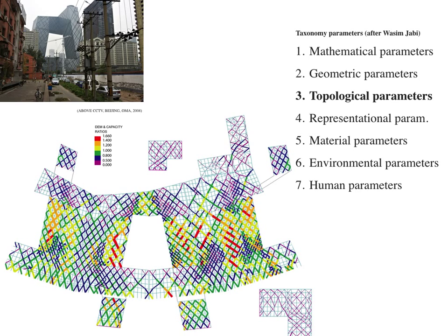In BIM, for example, a distinction is made between isolated geometric constructs, such as a cuboid, and a brick wall, which allows us to know how many bricks it has, its own weight, structural strength, cost, etc. Representational parameters allow us to describe some physical properties of what we are modeling. They also allow us to aggregate the information so we can report overall values and quantities.